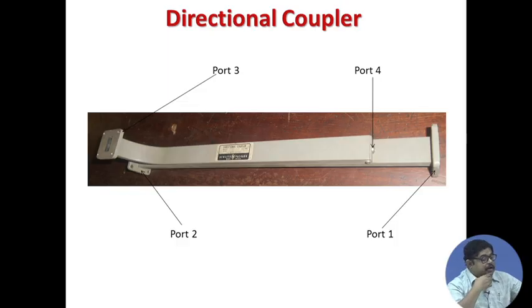This directional coupler, you see, has 4 ports. The main power is fed in here, port 1. This is port 2, from which that power goes. So, there is a main line here; you see there are 2 waveguides, one on top and another here. Port 1 and 2 are in the main line, which we call the main waveguide. This is an auxiliary line, where you have port 3. Actually, port 4 is there, but in many applications port 4 is inaccessible to the user.